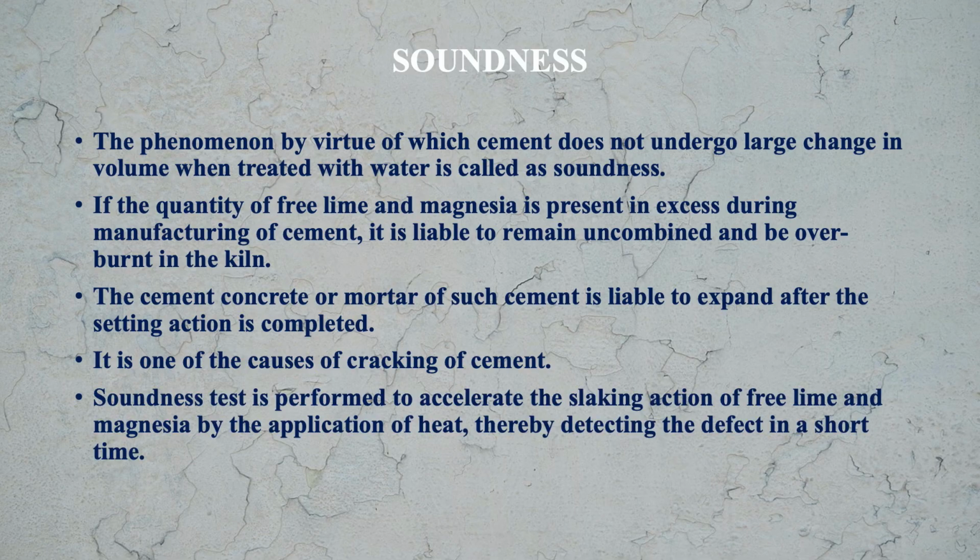Now the soundness test is performed to accelerate the slaking action of free lime and magnesia by the application of heat, thereby detecting the defect in a short time. Otherwise, in the natural process this defect will take a lot of time. So by accelerating the slaking action, we can detect this in a short time.